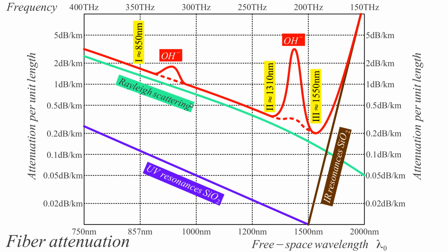It's not a crystal. So molecules are not arranged in any order, and we have Rayleigh scattering on these randomly positioned molecules, and this Rayleigh scattering, which increases with the fourth power of the frequency, is a significant contribution. So actually we have the minimum attenuation at 1.55 micrometers, when we reach this magic value of 0.2 dB per kilometer, minus is missing here, to simplify this drawing.